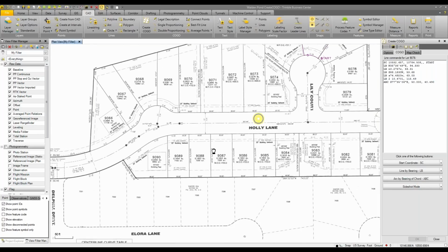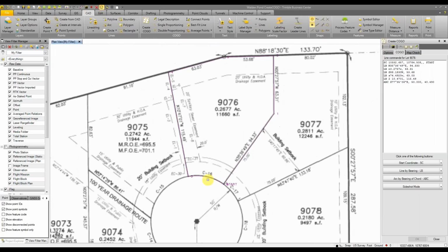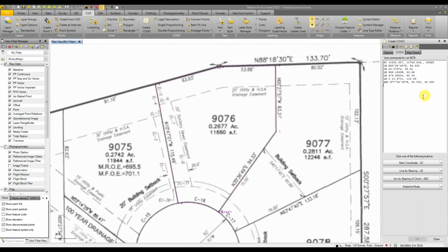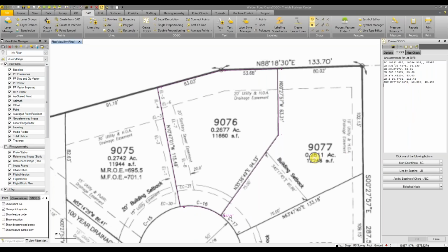Let's see how that turned out. Excellent. And there we go. There's our parcel, directions done, and 7 lines of text. Not bad. If you draw the arc and it's curving the wrong way, that's controlled by the sign on the radius. So if this was negative 50 feet, it would curve the other way. I had it the right way first time though. I'm a natural.